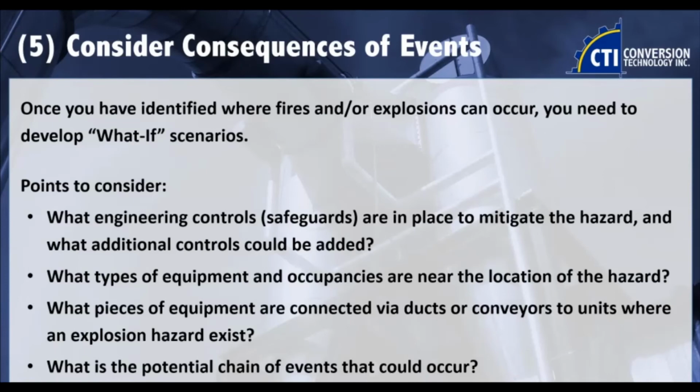How can it propagate to upstream equipment? Can a chipped hammer be a burnt ember going into your dust collector? What safeguards do you have in place? Engineering controls, administrative controls. What type of equipment do you have? Is it near an occupied location? What are the potential chain reaction events if something happens, a secondary explosion?